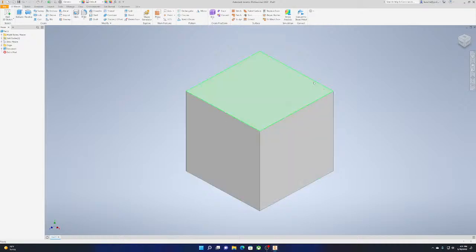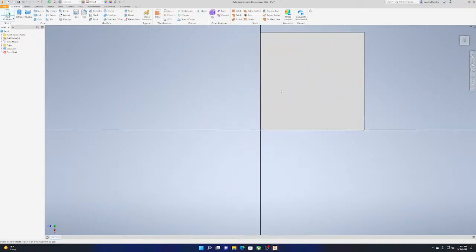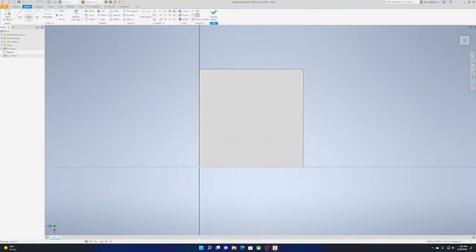So what we're going to do is I want to get circles. I want to cut a few circles out of this. So I'm going to click on Start Sketch again, but you can see that this time around, we didn't get the option of choosing our plane. No XZ, no XY, no YZ axis. Since this is a part, we can now just start editing on top of this. So I'm going to just go to the top, right here.